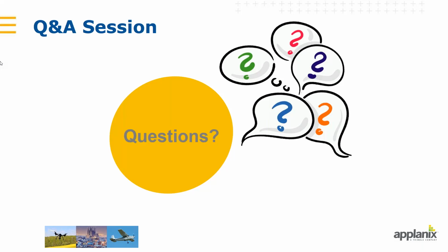Then another one, what is the expected accuracy for PPRTX? Yeah, so as you mentioned, Christian, we'll have to be in a, let's say, open sky terrain right now. And if you're in an open sky environment, then the expectation is you can achieve 3 centimeter horizontal RMS and about 5 to 6 centimeter vertical. Again, this is probably not occurring if you're in a dense urban environment or even foliage areas where you have outages and multipath effects, because that may cause the filter to reset.